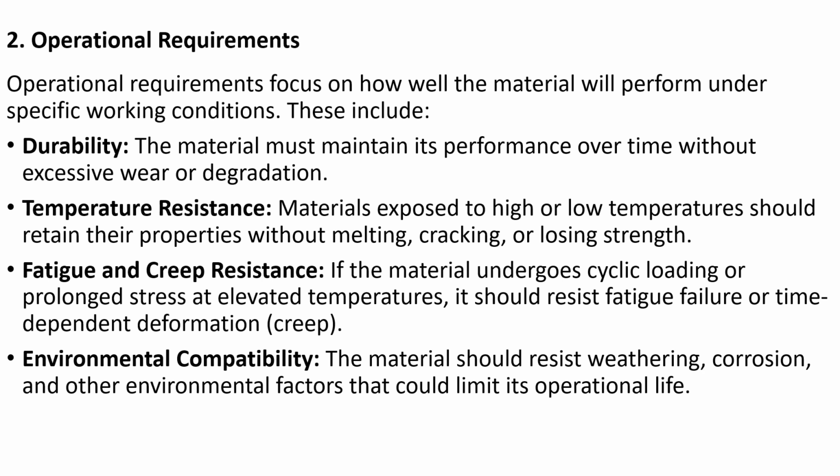These factors ensure materials remain functional and safe throughout their service life. Let's take an example, turbine blades in jet engines. They require materials like superalloys that maintain strength at high temperature and resist thermal fatigue.